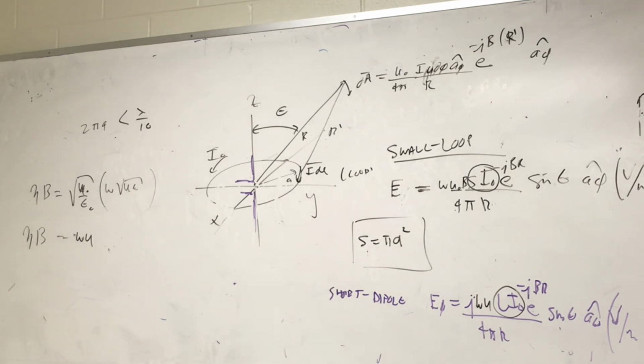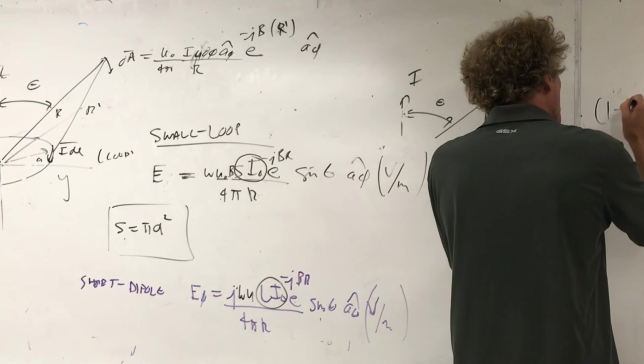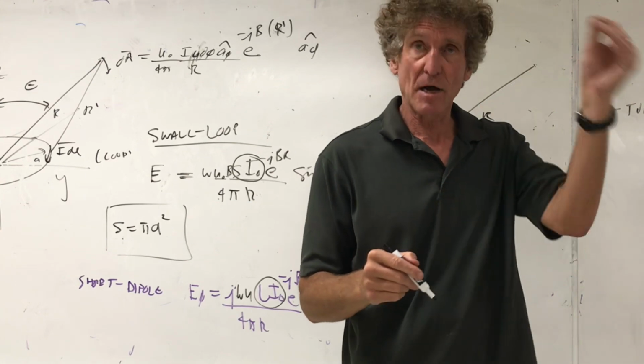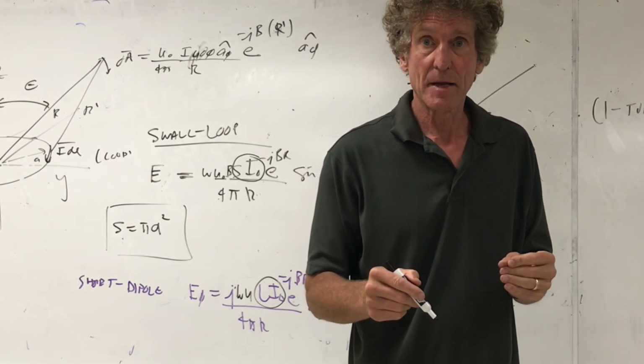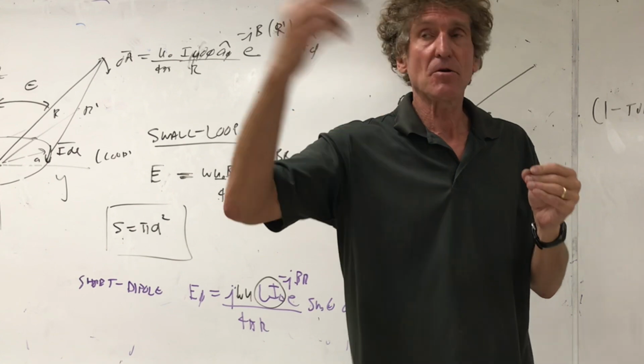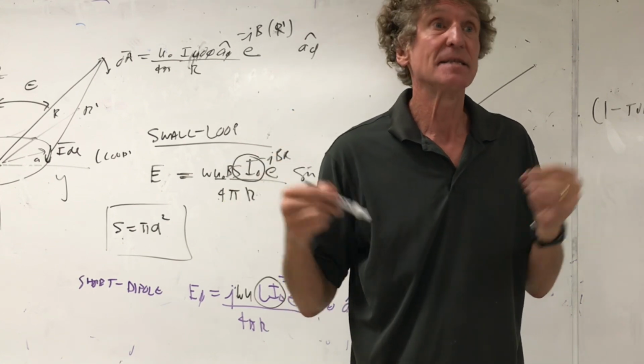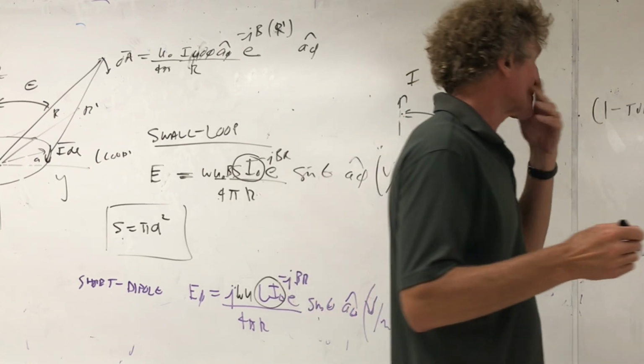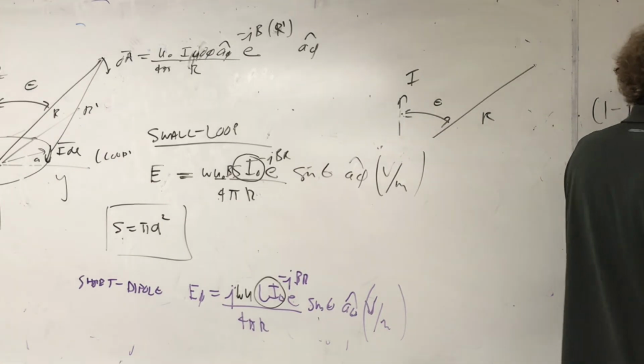Now coming over here, the big difference, and this is for the small loop, is the radiation resistance. And write this down for one turn, too. So if we have multiple turns, we multiply by N. Y'all with me, class? Because each time you have a turn, you're adding a series antenna, you might say. You're adding another small loop.